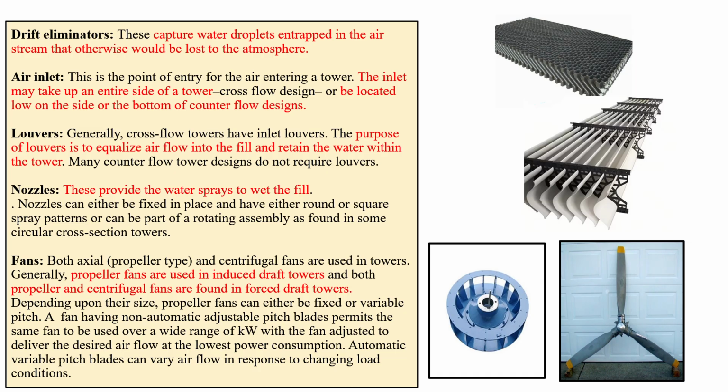Different types of nozzles are available as per design requirement. You have to select. Then the fans. This is the FD fan. It can be propeller type or centrifugal type. But in the induced draft fan, it will be simply propeller type. Centrifugal type blades are not used for the ID fan, but for the FD fan it can be used either this or that.